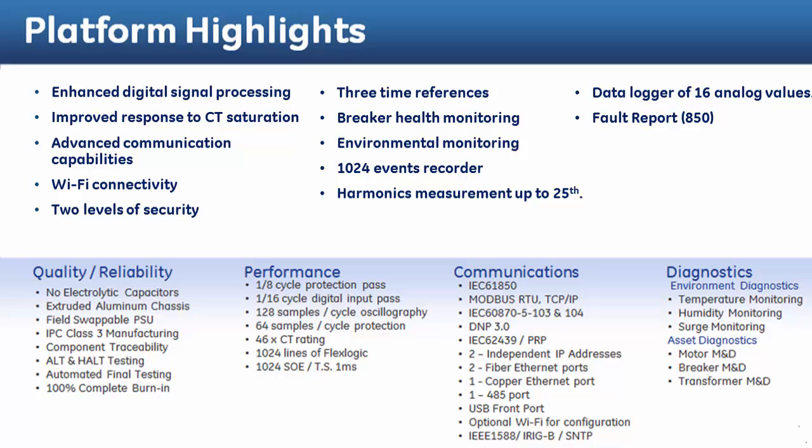And FlexLogic tools consist of 1024 lines, which gives the user maximum flexibility. 8 series can store up to 1024 events locally in the relay non-volatile memory, which means even if the power is off, these events recorded are still saved.